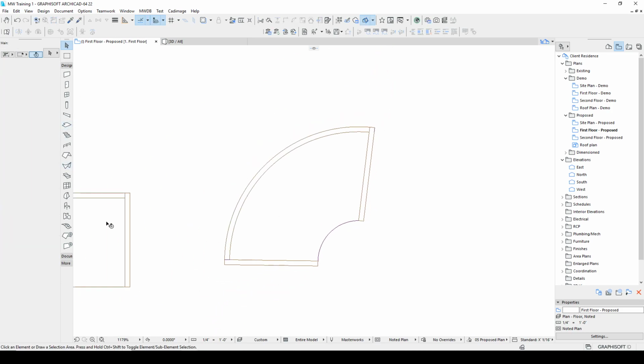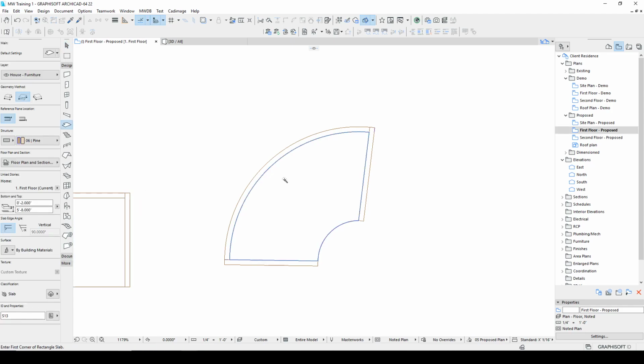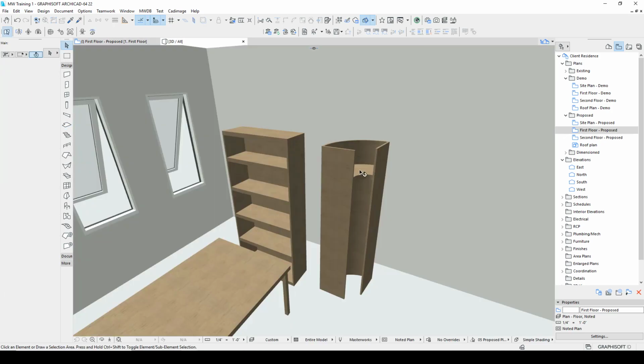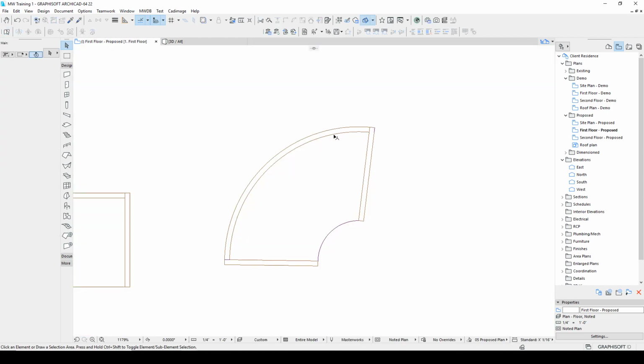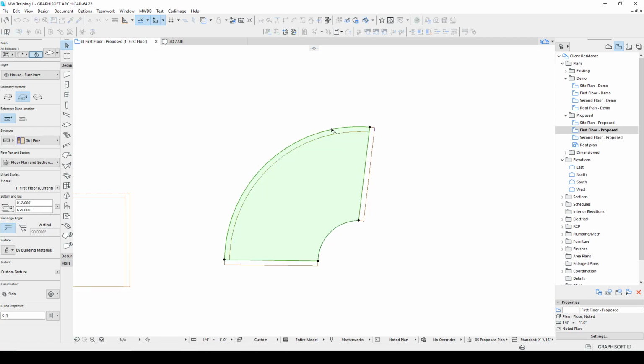And then I can pick up the properties for this is the top. You can see the 5'8". Click there. Hit F5, move it up. Now it's inset, so we're just going to take this and move it out, copy.